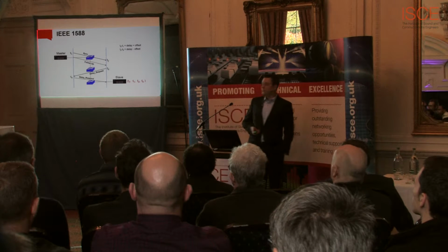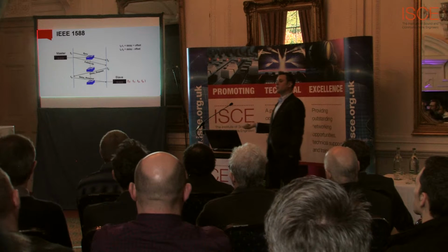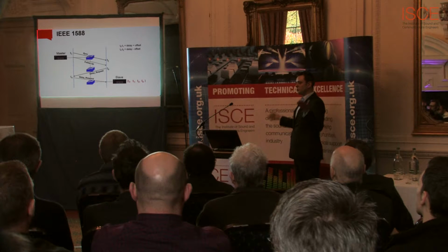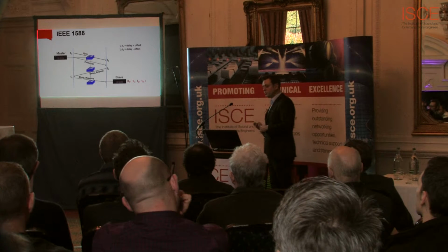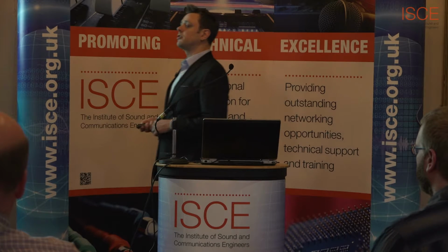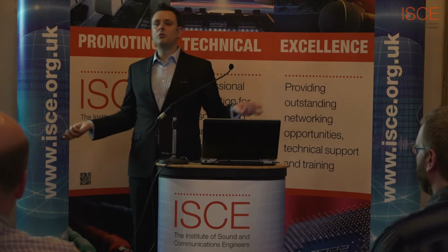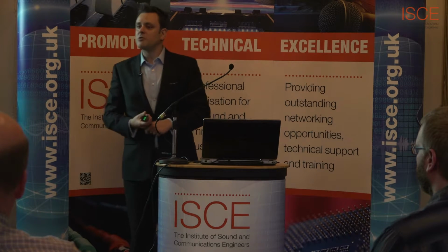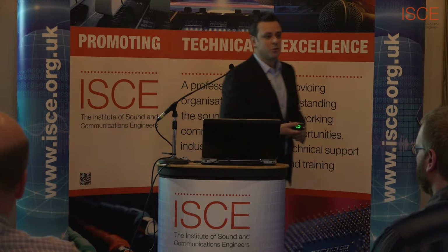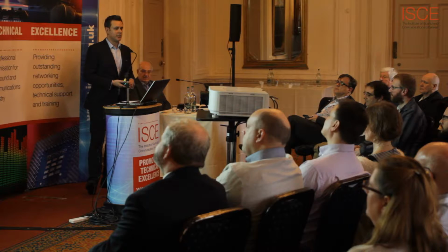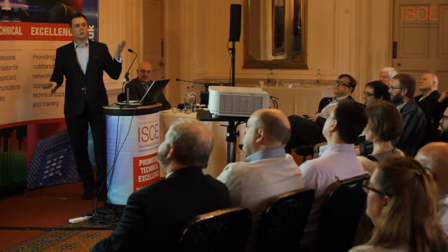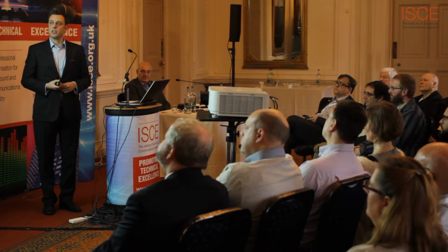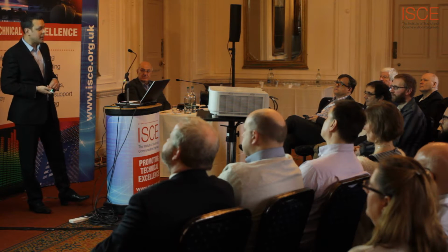So now the slave knows that if it subtracts T1 from T2, it knows the delay plus the offset between the two clocks. And if it subtracts T3 from T4, it knows the delay minus the offset. You put it the other side and you know the offset. So rather than using 750 packets to solve the problem, you use a couple. And now both clocks will be synchronized because they know exactly how adrift they are from each other and they can adjust their own clocks. That's 1588, and that's how Dante solves it.